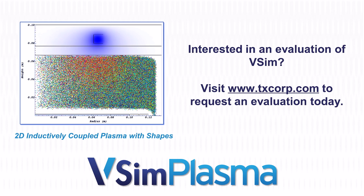Is there any limit to how small or how large the time step can be in these simulations? The major limitation on the time step is dictated by having to resolve the RF period or the oscillations that you want. For example, when we're only resolving 13.56 megahertz, we showed that you can take 20 time steps and resolve that oscillation pretty smoothly. That's the main limitation on the time step because the implicit solve itself is stable. Other factors that might change the time step are resolving the plasma dynamics, such as the collision frequency or plasma oscillations.